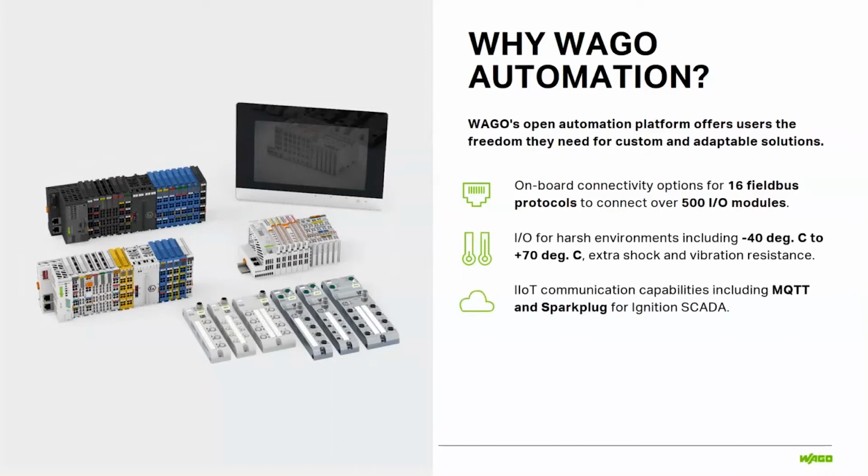We have IoT communication capabilities built in, including options for MQTT and Sparkplug for Ignition SCADA, which obviously we're going to be talking about today. We also have security features built in, including a built-in VPN, TLS encryption, and whitelisting and blacklisting options right off of the PLC.